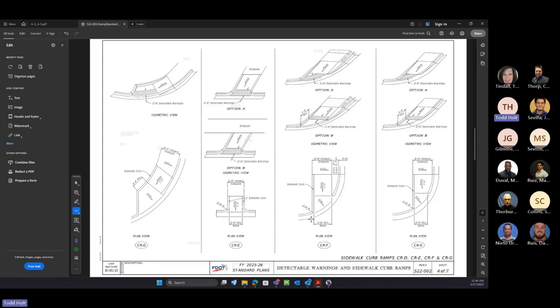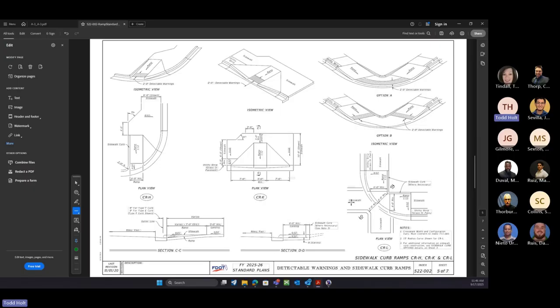It's different from a simple cell, building your references off that. So maybe a flow line, curb back top, sidewalk front, sidewalk back. We can build the curbs in there. So different ways we can build those different civil cells in there, and have a left or right, looking at the different ways to build that out.